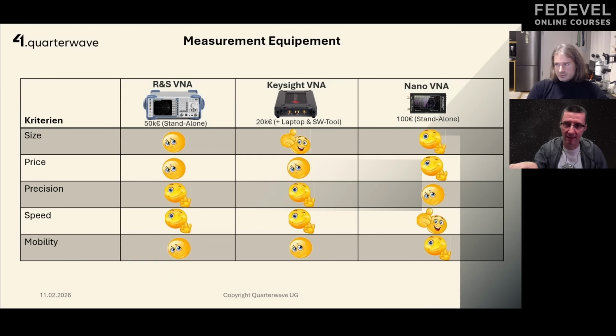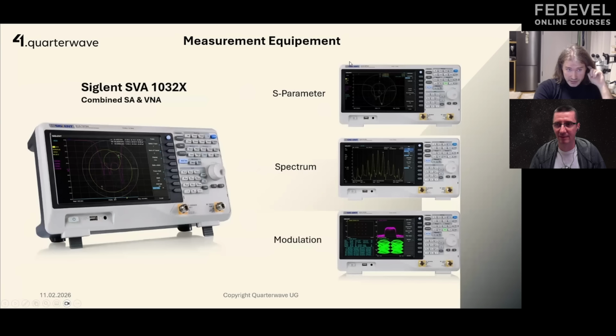So I would like to point out, we can see on the display exactly the charts what you showed at the beginning, when we have to move the impedance of the antenna to 50 ohms by adding a capacitor or inductor. Yes. Exactly. And what I use personally, I can also show you.